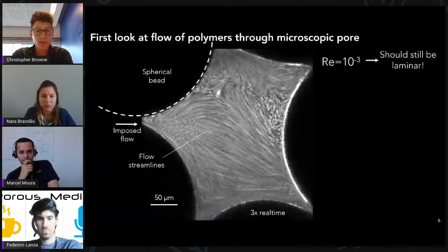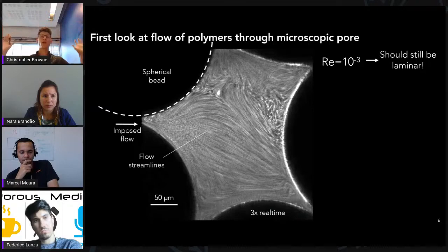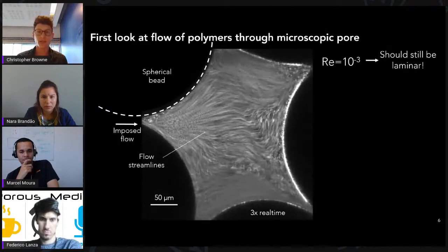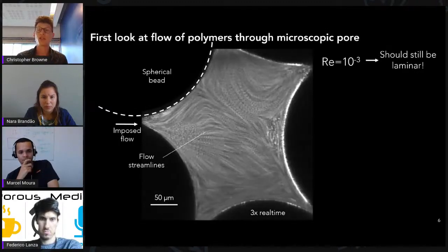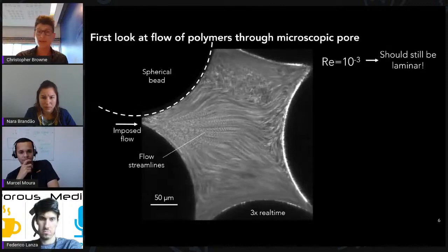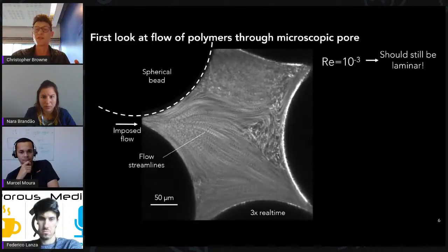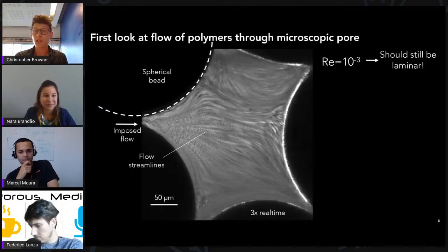This is different if I crank up the flow rate a little bit. So I'm still at low Reynolds number. Anybody from an engineering background might have told you that this should be a laminar flow, but if you actually image the flow, instead you see this really rich dynamic flow that's changing in time. And we can let this go for hours and hours, and we'll continue doing this. I've actually done this for 2 days before, and the flow keeps fluctuating, right?